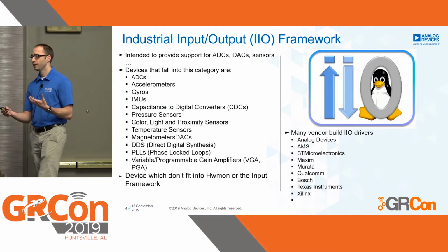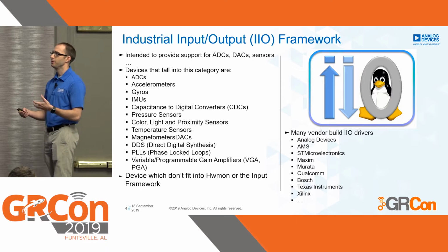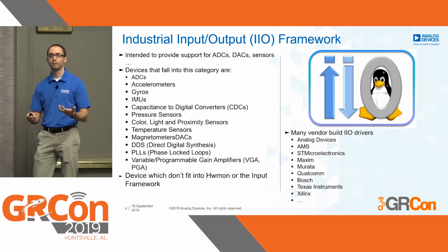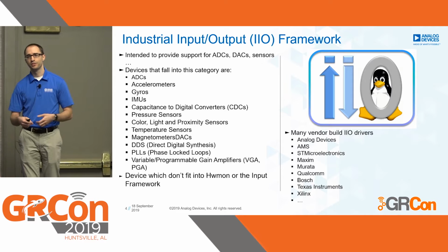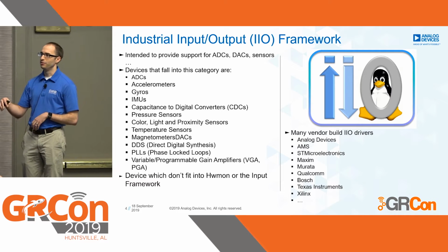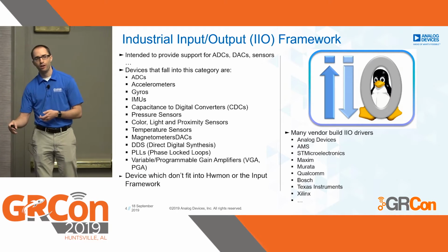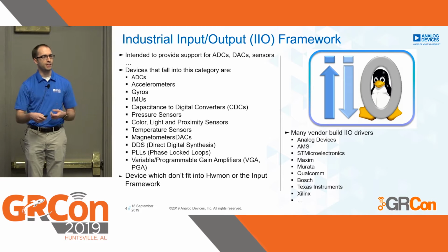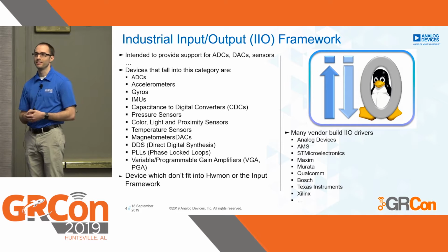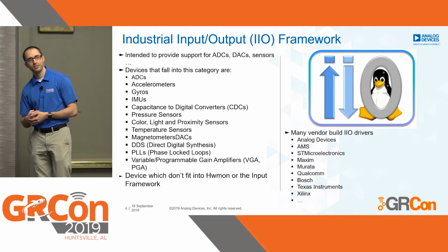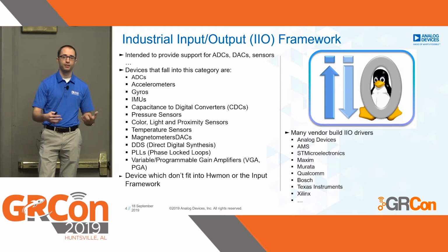Okay, let's get into the basics of IIO and libiio. Now, if you're not familiar, IIO stands for the Industrial Input-Output framework. This is a kernel framework that's designed for generic ADCs, DACs, sensors, the things that don't fit into HWMON or the input framework, which is for keyboards, mice, that kind of thing. So it's perfect for the devices that ADI works on. But this is not an ADI-only thing.